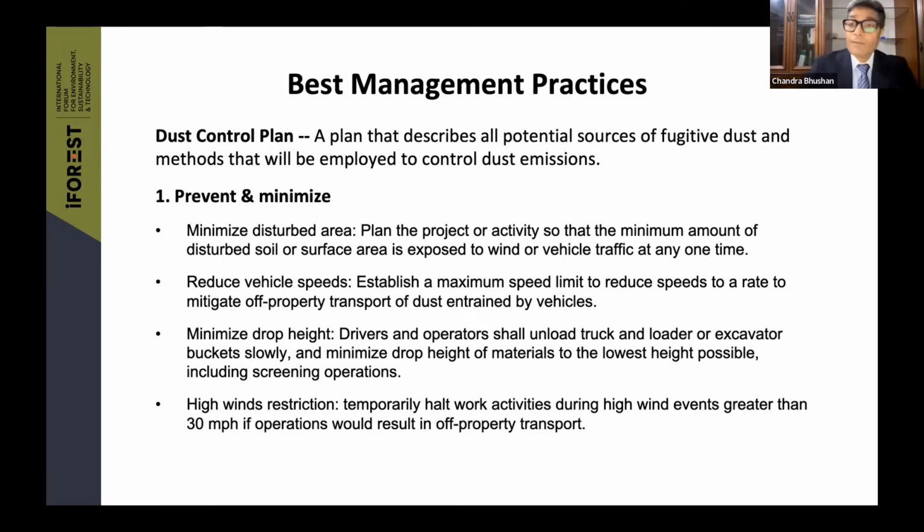You will have to minimize the disturbed area. You must design the dust control plan in a way that minimum area is disturbed at any one point of time, and that you are not cutting all the trees, you are not excavating the entire area. Those are not required. So minimize the disturbed area, reduce vehicle speed within the site,